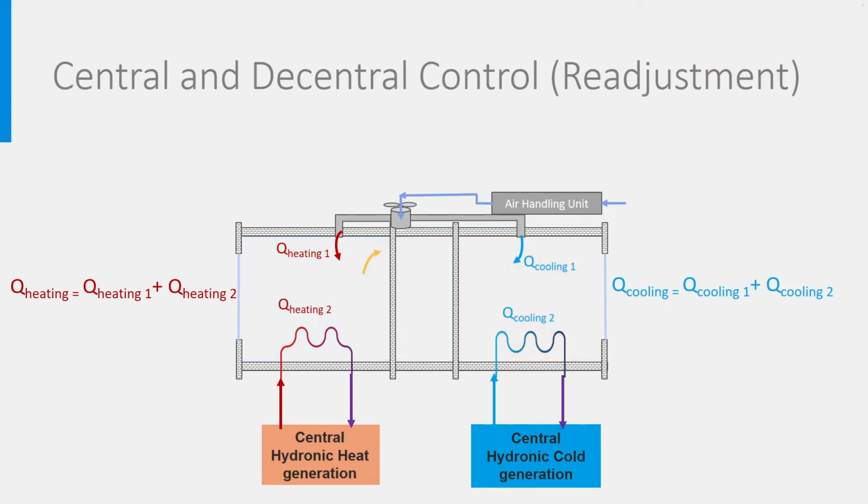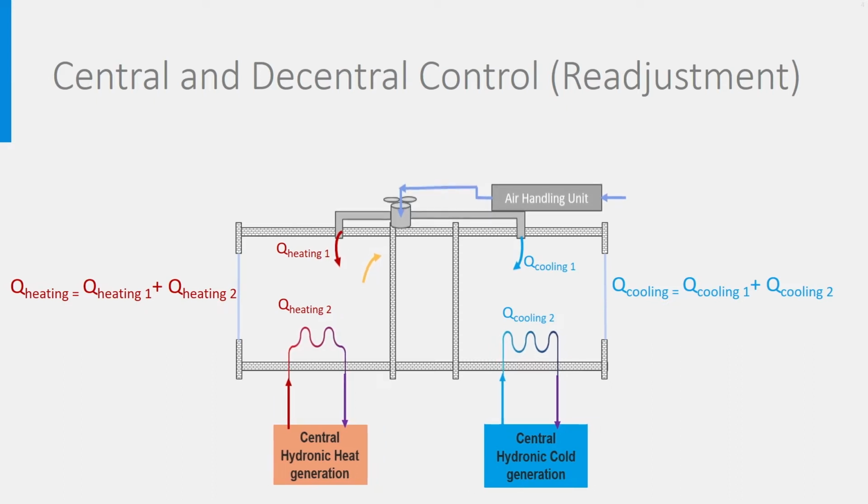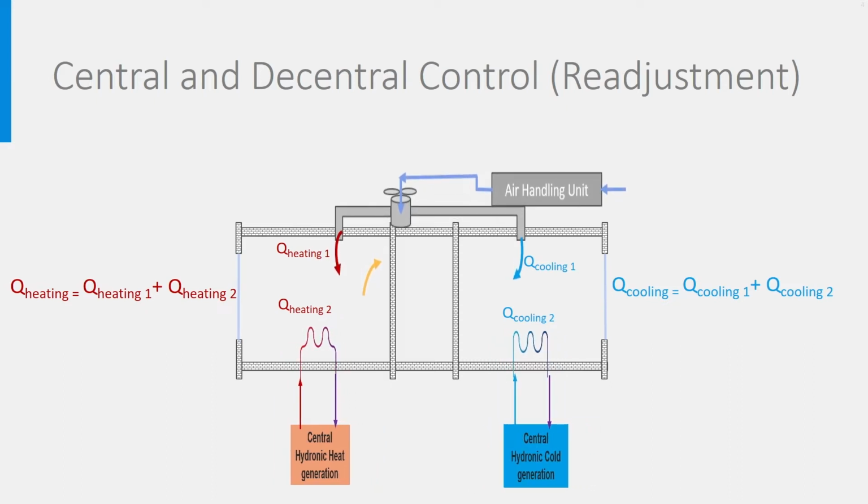There are many variations possible between the all-air system and the hydronic one. Hydronic is just another word for a water system, I remind you. The air system can be designed larger or smaller, just like the hydronic system, but of course in opposite direction, in order to provide the total quantity of heat and cold needed. In another lecture, we described how zoned HVAC helps with a better control of ventilation, temperature and energy usage at zone level. The room hydronic system helps to control even more, at room level this time.